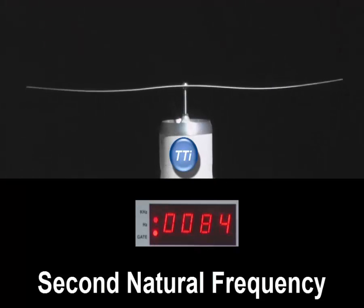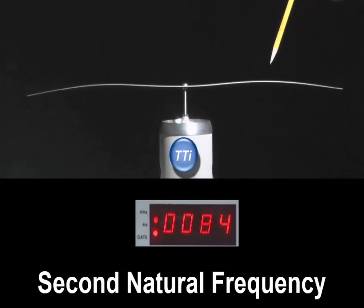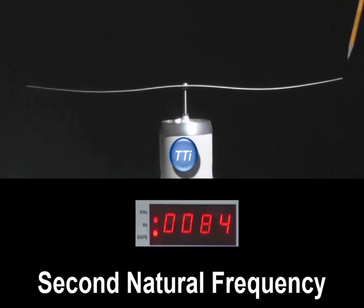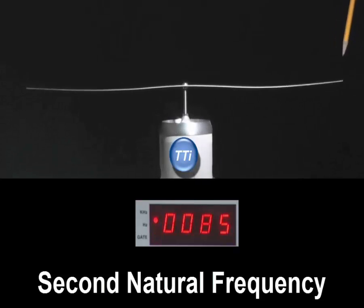Here we are showing the second natural frequency with the strobe light, and we can see the node point is about here somewhere, and this part of the beam is out of phase with this part of the beam. The beam is still shaking just over 80 Hertz at its second natural frequency. We've just slowed the motion down by looking at the strobe light.